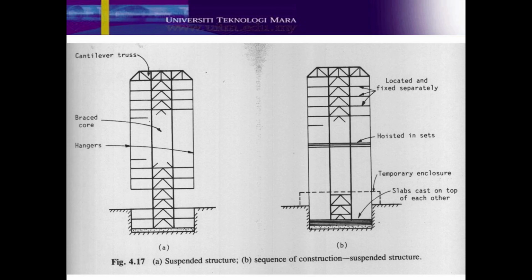Consists of central cores, with horizontal cantilevers at roof level with vertical hangers of steel cable, rod or plate attached. Architectural and ground floor free from columns is shown in Figures 4.17 to 4.18. Structurally inefficient in gravity load transfer, it should limit the maximum number of floors to be supported by a single hanger to 10 floors only.